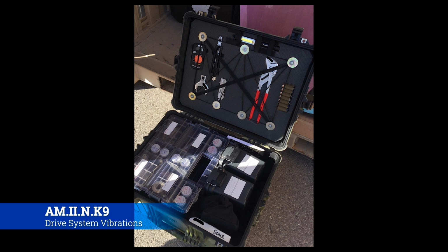So whenever you go to do balance, even if you have a tool, a computer that's telling you you need to add so many grams to this blade, the computer can't see where the blade is. It can tell, hey, look, this blade is clearly not weighing 500 grams because it's behaving in a way that it shouldn't. So therefore, you're going to have to add some weight to it, or maybe take some weight off of it. But what the computer doesn't see is where that weight went missing. So you have to play with the machine a little bit.